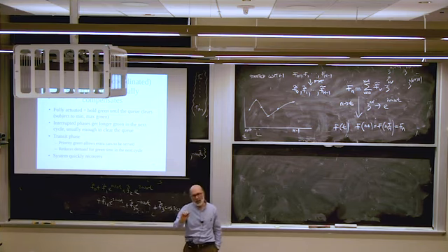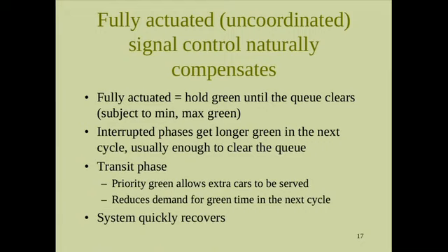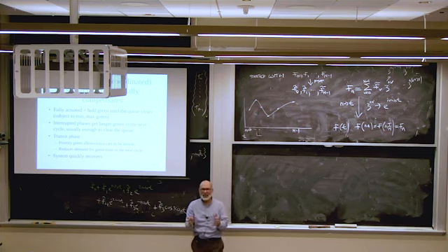If we increase the sensitivity, then that'll detect a bike. But then the danger is it will also detect a car in the next lane over. So there's a trade-off there. If we want to detect bikes, we use a figure 8 configuration, and then we try to educate the bicyclists to drive right down the middle of that figure 8, and that's where you'll get picked up the most.